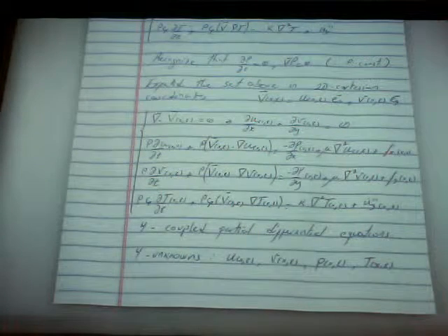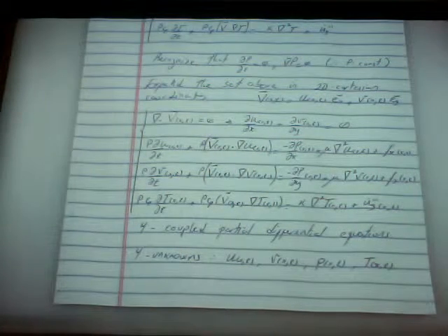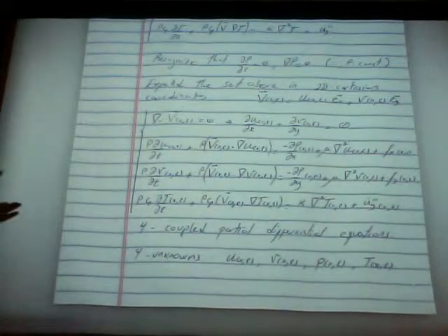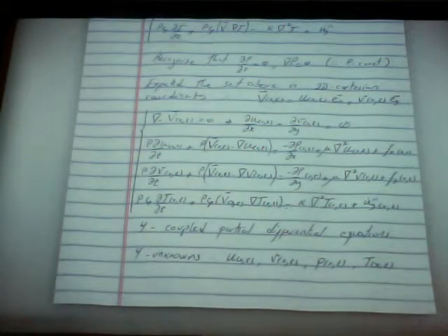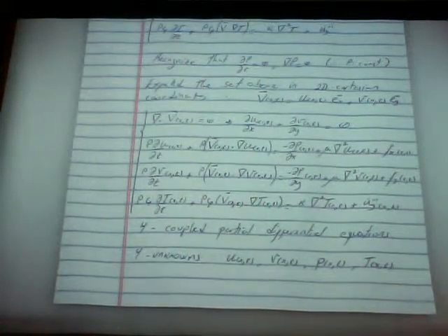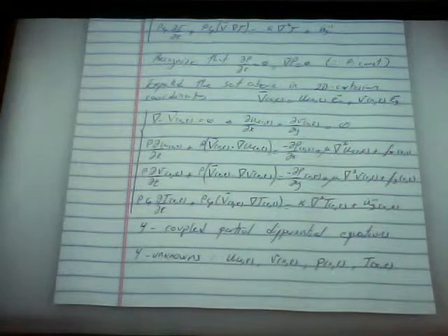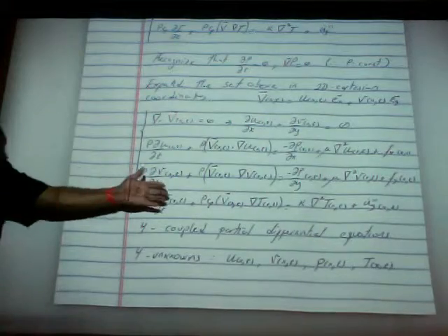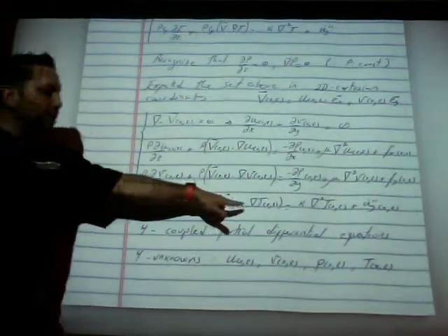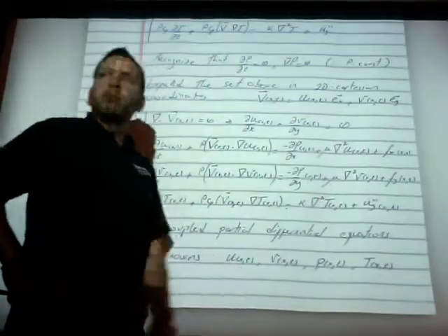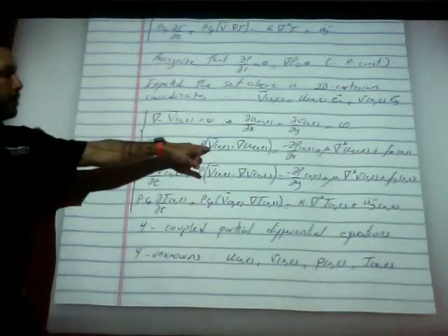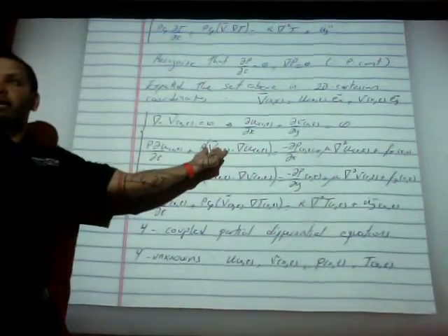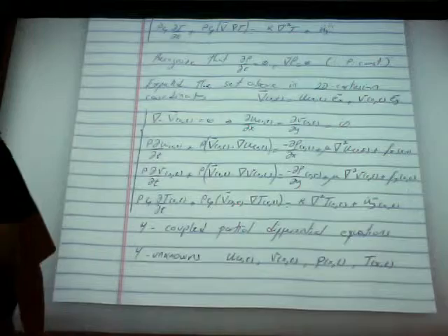They're partial, second order. Now, what's also complicated about these equations, which is the key complication here? Well, besides the fact that you have coupled partial differential equations, you have 2 more things that would make it extremely complicated to solve these problems. The other thing is that 2 of these equations are nonlinear. Okay, this equation is linear. The unknown is t. The t doesn't show up multiplying t anywhere, right? But look at here. This one has u times the gradient of u. Well, this v has u and v in it, right? It's multiplying u. That's a nonlinear term.